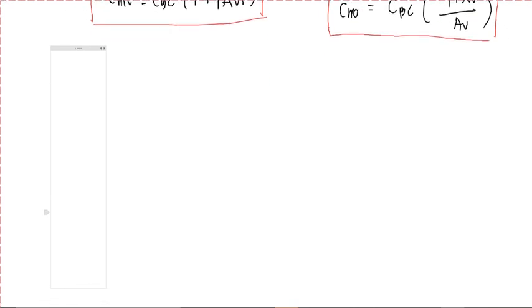Okay, take note of the things we need to consider. First, the given capacitances will always be present. What are the given capacitances? We have your C1, we have your CC, the collector coupling capacitor, and we have your CE or the bypass capacitor. This will be present in our circuit. Next, in low frequency response, we no longer need to consider the imaginary. No imaginary capacitance.